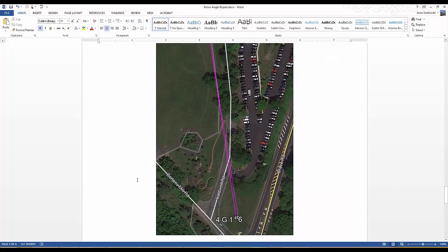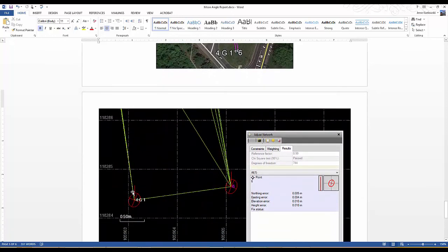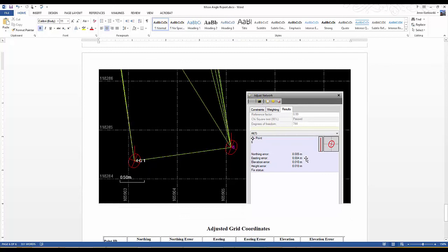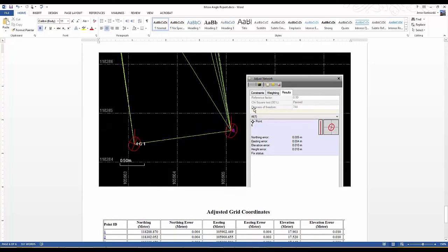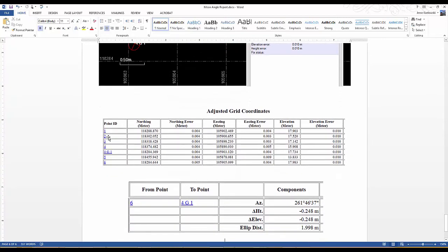All right. And thought I'd just also include the positional tolerance of 0.6 after making all of these measurements in meters, 5 millimeters by 4, and about a centimeter in elevation. And that's at 95% confidence. And I figured I would just tabulate here all the points with their coordinates and their positional tolerance at 95% confidence.